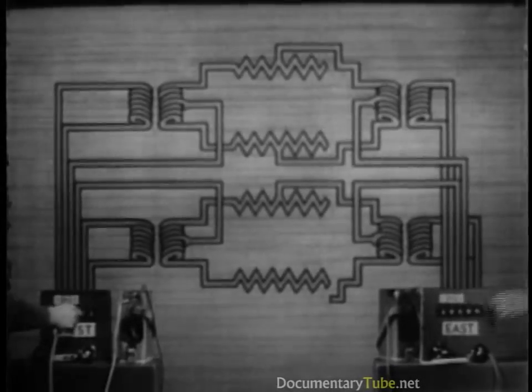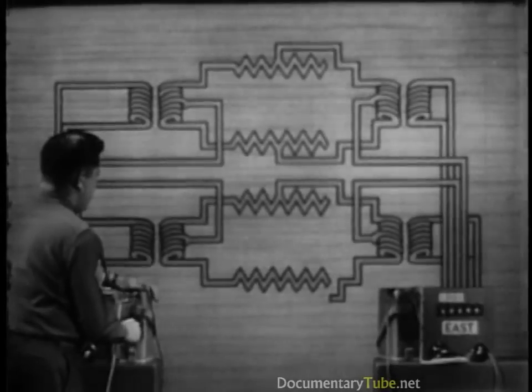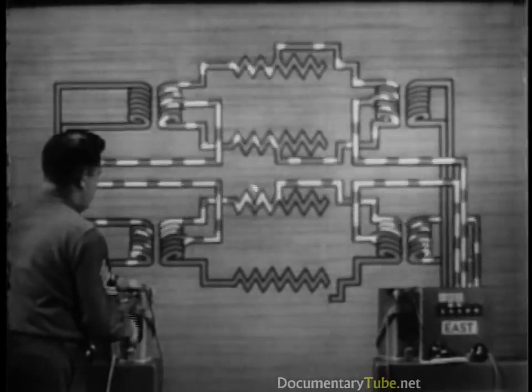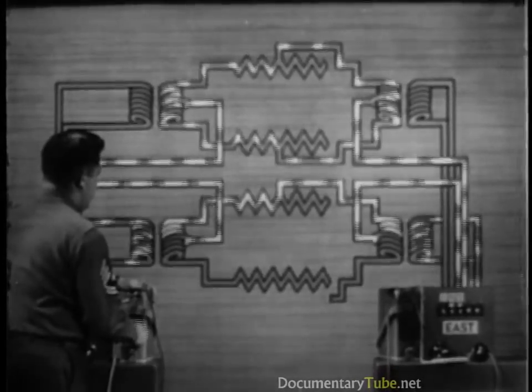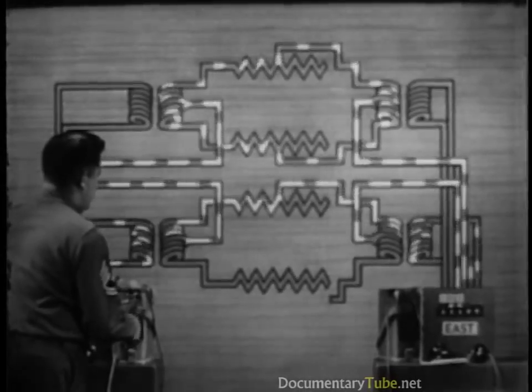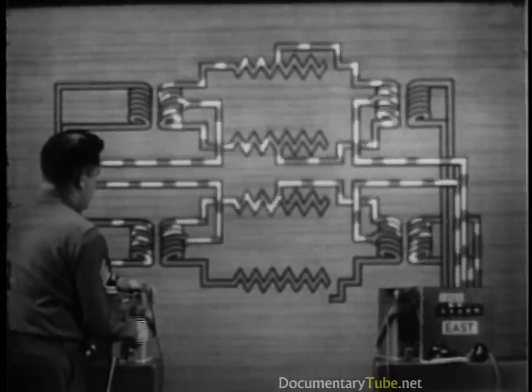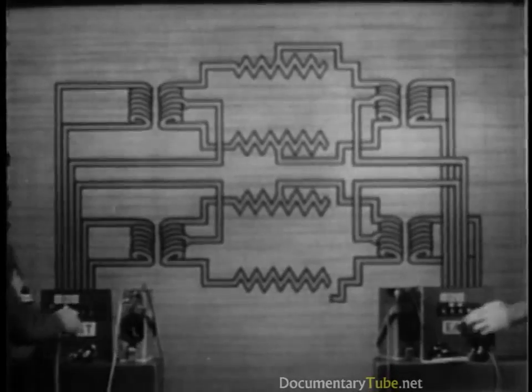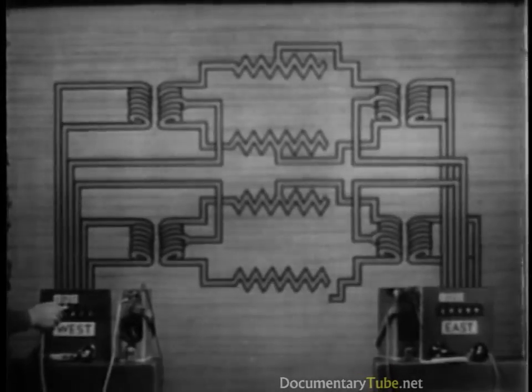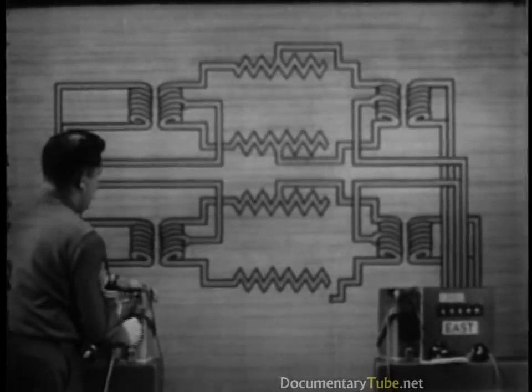Ringing on the faulty side circuit produces a weak current, which finds a return path through the phantom. This causes interference in the phantom. The unbroken side circuit operates as usual.